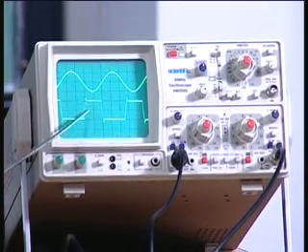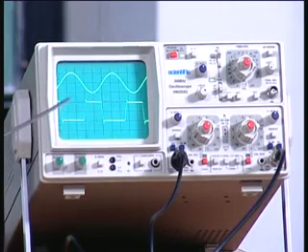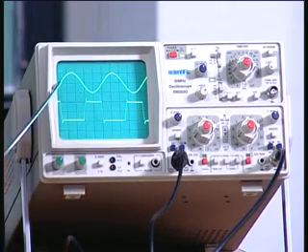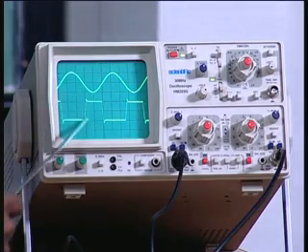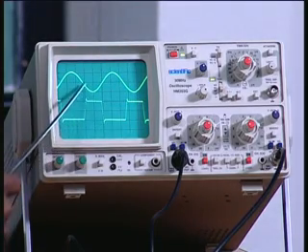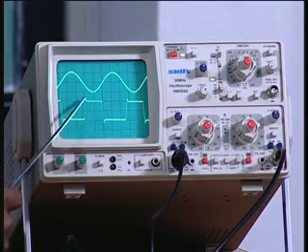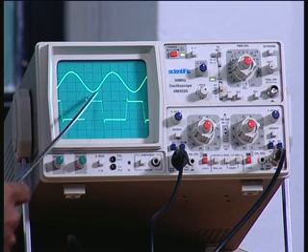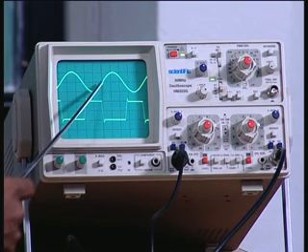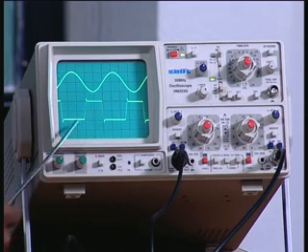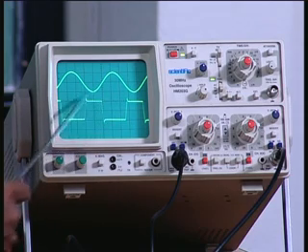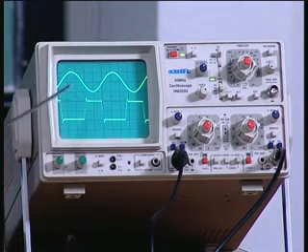This is the output. Now if you carefully observe, the 0 of the sine wave will be somewhere here, and so it has just slightly crossed that 0. Immediately you find it goes to plus VCC on this side, and whenever this again crosses that point, it comes back to minus. These two are actually minus 15 and plus 15, or minus 12 and plus 12, something like that.